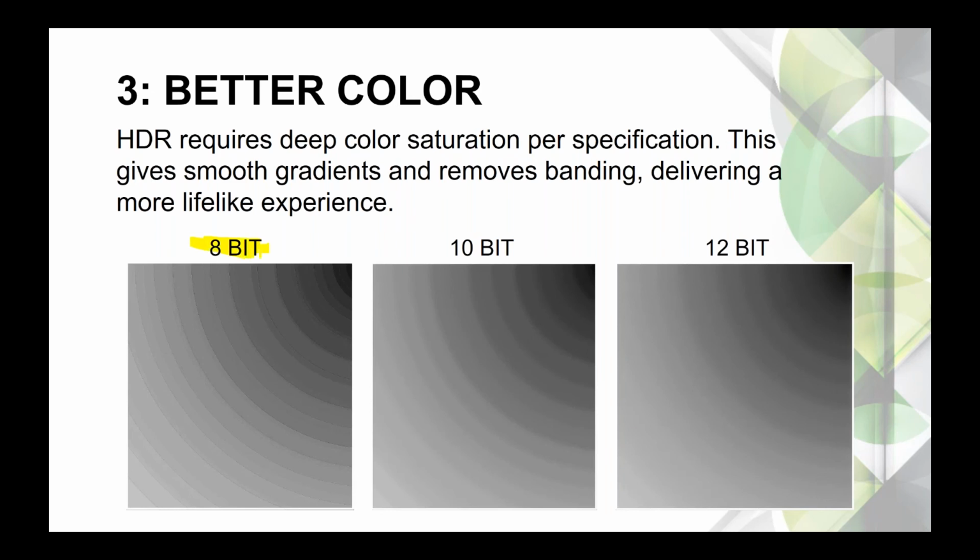In a 10-bit system, that number goes up to 1024. And in a 12-bit, it goes up to 4096. So by going up to 4096, we basically eliminate banding. In pictures, this is extremely important. And if you remember the previous slide, we said the normal output of a UHD player is 12-bit, and that's the same with streamers and the like.